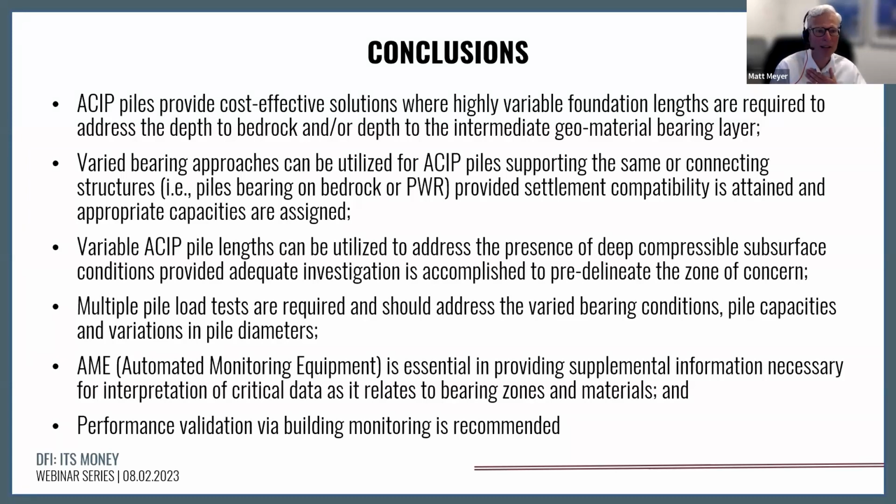And in my opinion, there's really nothing better than running those settlement calculations, coming up with that solution, implementing that solution, and then verifying the settlement performance of that structure with physical settlement monitoring, or maybe even further kinds of monitoring, such as strain gauges, other kinds of monitoring devices. So I would encourage everybody on this call to really think about performance monitoring as you look at your projects in the future.